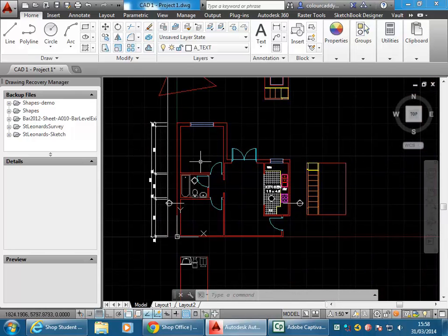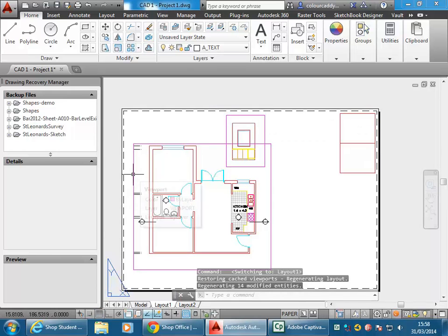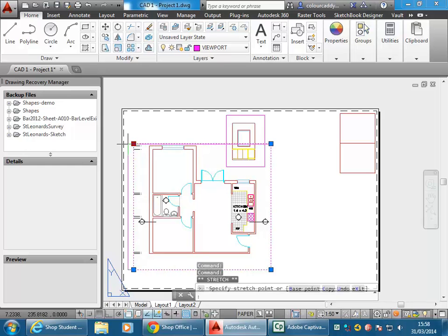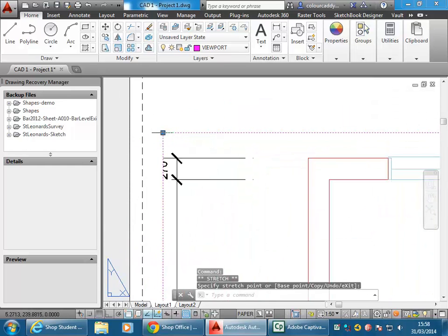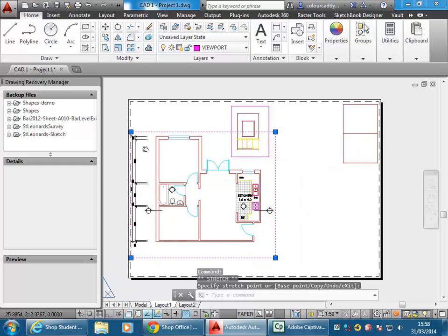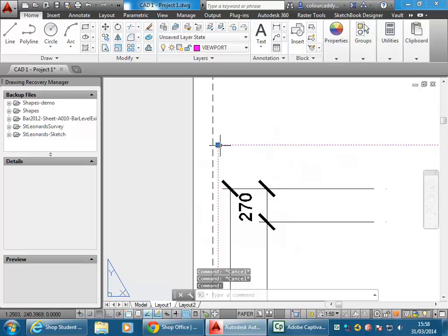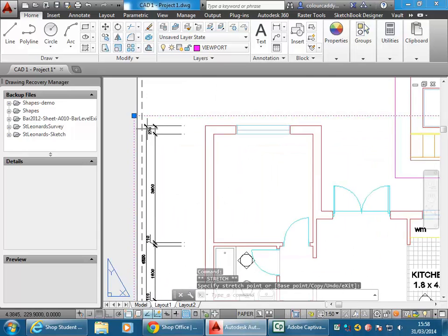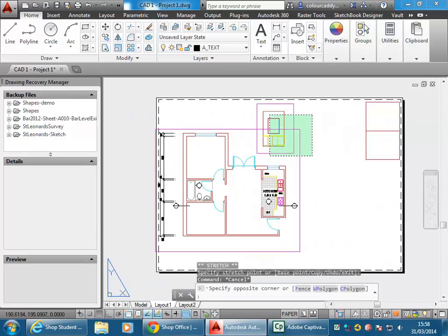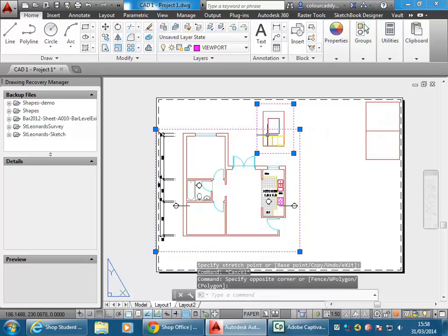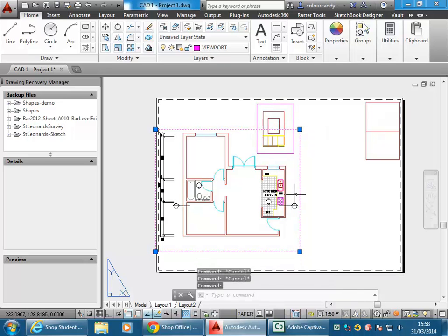And then, just to try that all together, if I look on the page now, the dimensions are cut off, but the viewport can be made bigger so that we can read them. It's going off the page, but then that can just be moved across. I'll show you a quick way, just by when you select the viewport, dragging where there aren't grips.